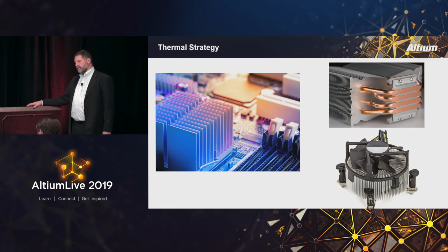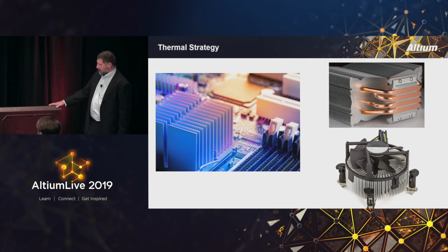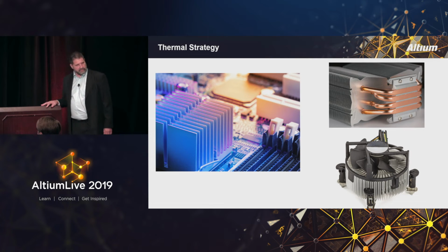And then what also matters is what your end environment is. Is this thing going to be inside a room like today, where it's fairly comfortable, or is this thing going to be in a hot desert? Is the end product going to be used in sub-zero temperatures? We need to know where it's going to be used, how it's going to be used, what the environment is. That's going to drive those thermal decisions. And there's very, very good modeling for these thermal issues now. The tools we have now for this are pretty amazing.